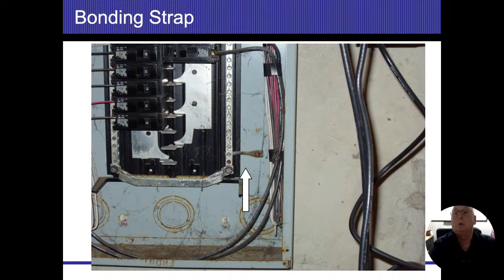All right. So one of the questions Mark asked, if the water pipes aren't used for grounding, then is it still important to jump past the water meter? And the answer is going to be yes. Because even if the water pipes aren't used to it, especially in our area, if I have a water meter there, it's very common. So the utility companies are going to be expecting to use that as well.